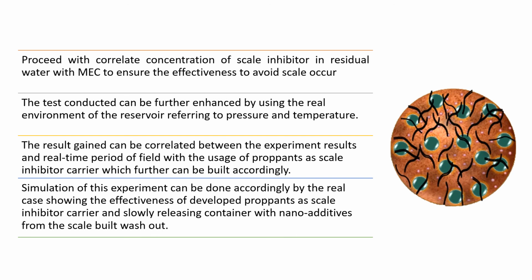And the test conducted can be further enhanced by using the real environment of the reservoir, referring to the pressure and temperature. The results gained can be correlated between the experiment results and the real-time period of the field with the usage of proppants as scale inhibitor carrier, which further can be built accurately. And it will be nice if the simulation of this experiment can be done according to the real case, showing the effectiveness of the developed proppants as scale inhibitor carrier and slowly releasing container with nano additive from the scale buildup washout.